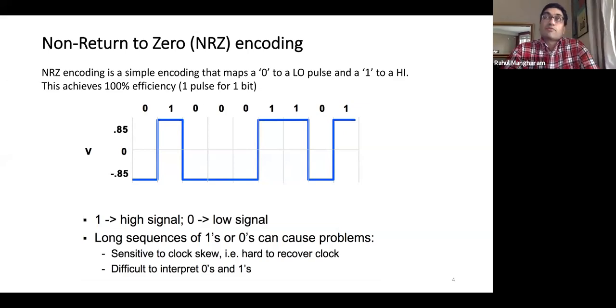So that's what we have in, say, your serial communication, right, where you set the baud rate. We have already agreed that, look, I will send you the data at 115 kilobauds, and I will format the signal where I have a start bit, I have a stop bit, and I do not have any parity bits.